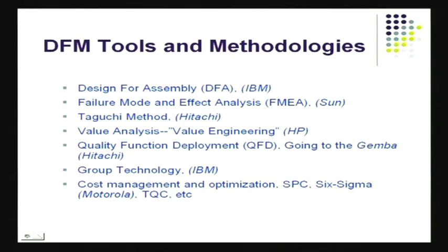He was able to come up with this special method where he used experiments, and we've seen many experiments in this lecture early on. There are special types of multi-factor experiments called orthogonal array experiments. These are utilized to find the optimum settings for the different design parameters when you're trying to design something. The same thing can be done for a process also, and you can come up with a robust design for the process or a robust design for the product itself.